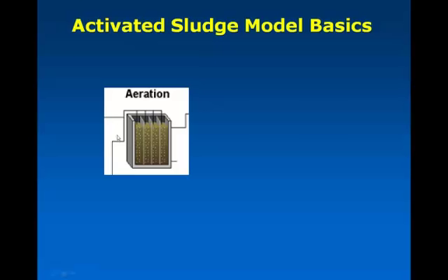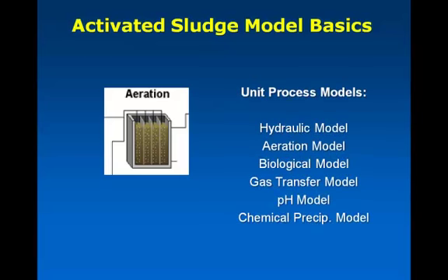This is a plug flow tank that we're showing here with some flow coming in. We can distribute that either in the front end of this plug flow system, or we can do some step feeding. We've got bubbles here to represent the aeration that's going on. There's really a lot happening here. There's, in fact, 6 submodels going on most of the time in this particular unit process.